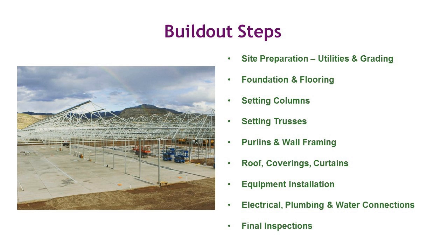And then once you have your coverings up, you can start framing around your different pieces of equipment, such as your fans and your intake vents. So then the next thing would be to install the equipment, which includes your heating and your cooling. Then once all your equipment's in place, you can bring in your electricians and your plumbers to connect for your heaters and for your water connections, your pad wall, or maybe you just have some hose bibs throughout the facility, things like that for cleaning things, and also for irrigation. So once all that's said, then you have your final inspection of all the connections and the structure itself.